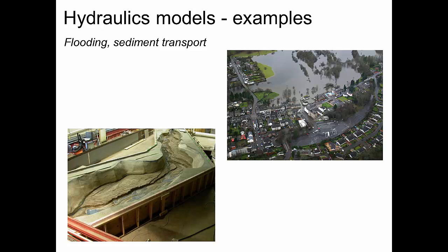We can use it for sediment transport and flooding. Again, you don't want to have to flood a real thing, so it's a lot easier to scale it down in a model and then test what happens when we have the 1 in 200 year flood, for example, 1 in 200 year flow down a river. And we can also scale sediment down and look at sediment transport and sediment modeling as well. That is notoriously difficult, actually, sediment transport, to do numerically anyway. So quite often experiments are the best way forward, just because there's so much going on, such complex physics.